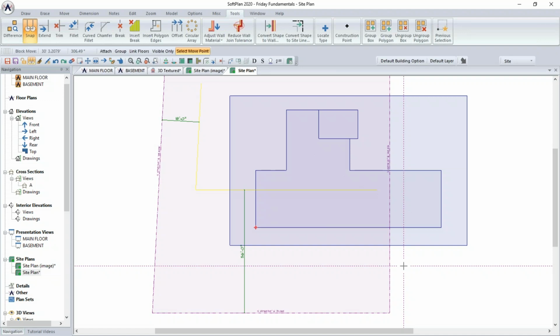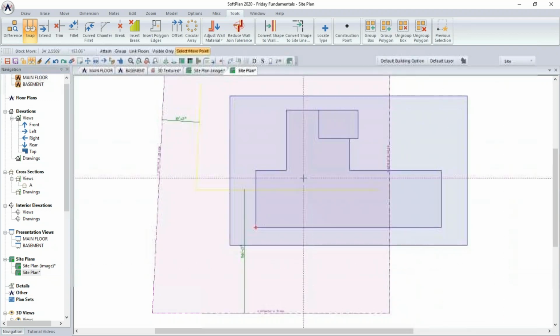The reference circle was saved there because the reference circle was already in the main floor plan at that same corner. So when you do generate a building outline, it creates a building outline of the perimeter walls, but if there's also a reference point already established, the saved site plan drawing automatically places the same reference point symbol at that same corner. So I've selected what I wanted to move, again, those three objects.